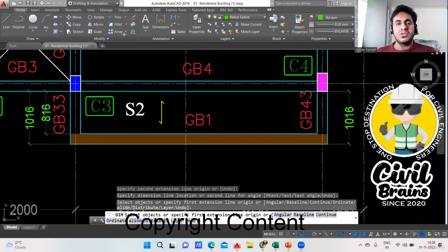But when you do the shuttering, this complete length you are going to take. That is okay. This length I got, I'll multiply this by the depth. I'll get this part shuttering. If I multiply this by 2, it will not work out. What is the reason behind that? The reason is that here when you do the shuttering, this portion, your shuttering is only from this end to this end. But whereas this part, your shuttering is from here to here. You're getting my point? That means this portion and this portion will not come into play when I go for this part of shuttering. In that case, you need to take shuttering 2 times.